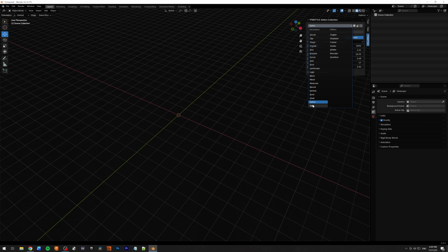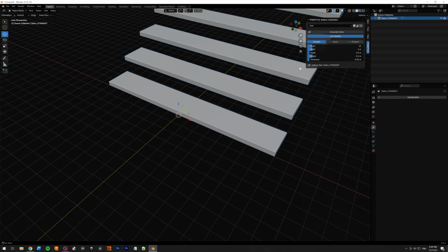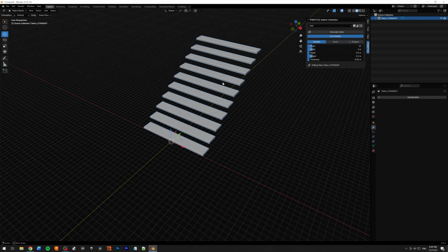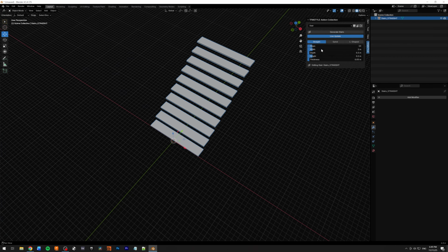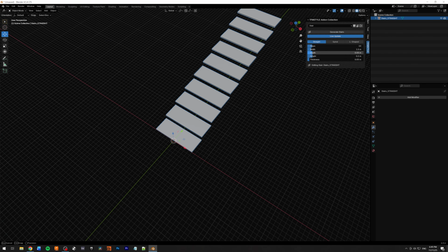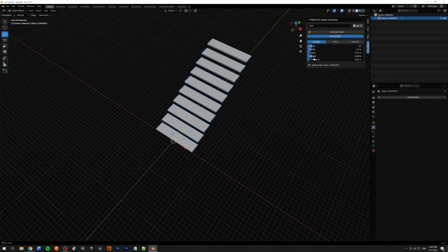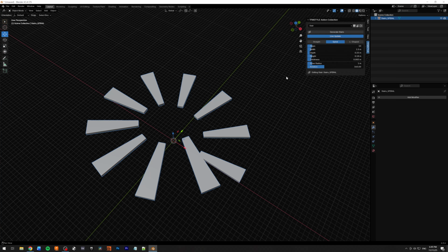And our last generator in our list is the Stair generator. So I'm going to click on that, live update, generate stairs, and this will generate stairs. That's pretty much it. You have the step count, the width, the depth, the height, the thickness, and you have a couple of different models.